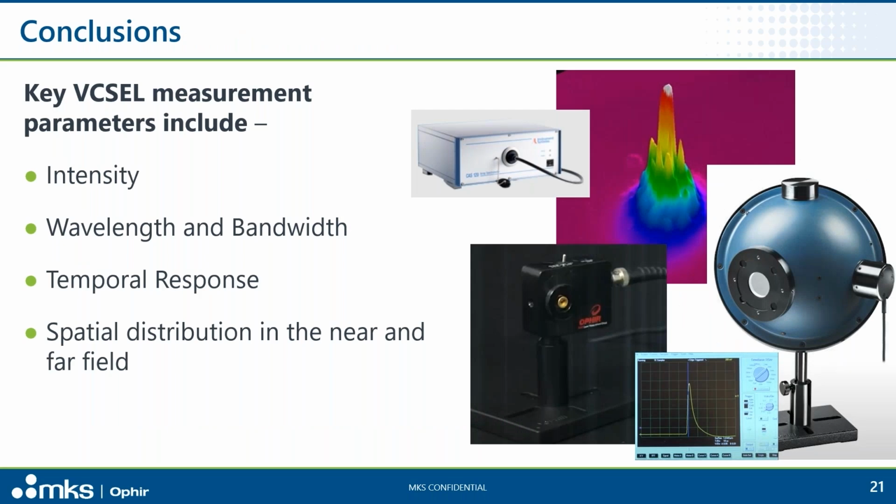Conclusions. The many challenges presented in the measurement of VCSELs and other technical light sources can be met with commercial systems or off-the-shelf components. Custom systems tailored to a specific application may be built from off-the-shelf components such as mini spectrometers with fiber optic input, integrating spheres with integrated intensity sensors, and pulse shape measuring fast photodiodes.